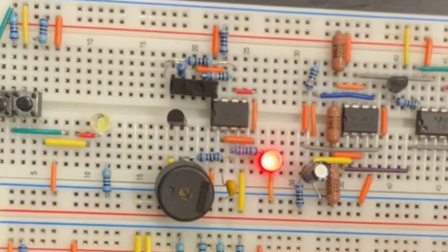This also applies in reverse, so when we apply changing voltage in the form of a square wave, the material deforms and pushes air, creating sound waves at the same frequency of the oscillating signal. This is the 2 kHz frequency outputted by the piezoelectric buzzer.